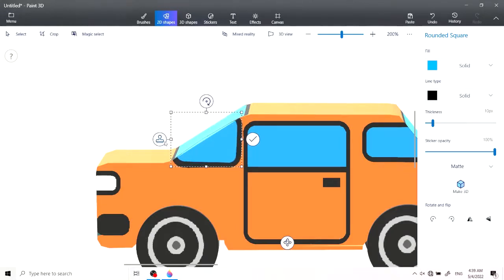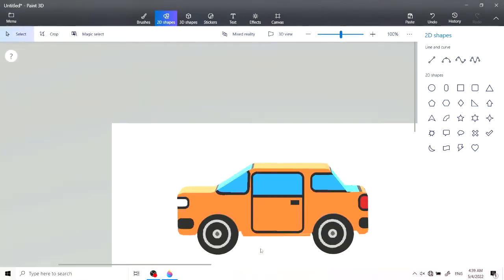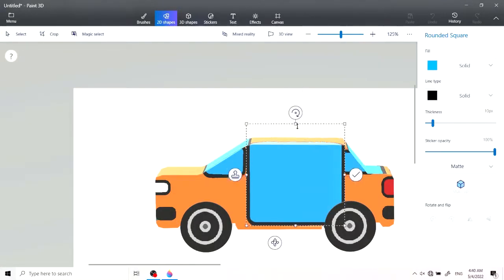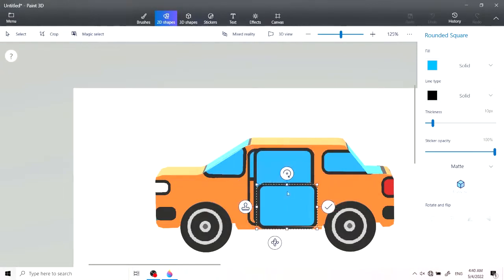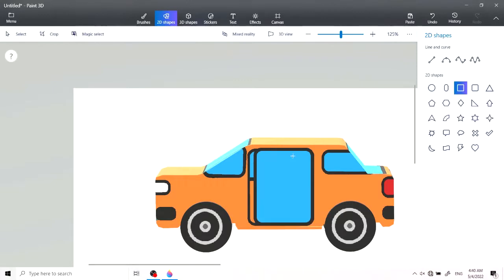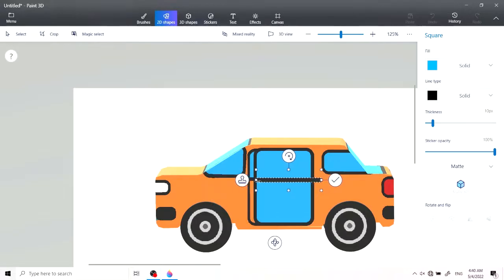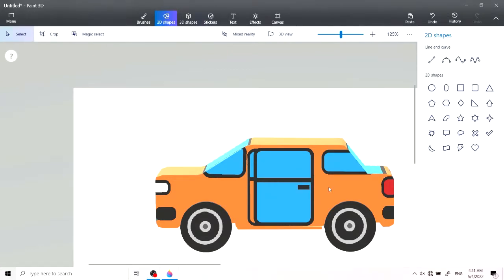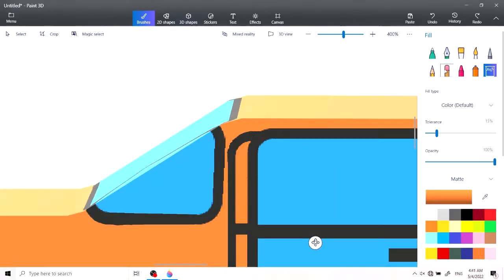But unfortunately the door is a little bit too close, so I'm going to need to correct the door as well. So I will use the geometric shape with fill in feature activated, and just align it over the existing door. What I did with the panel there, because I still had the panel active, I just pressed escape and it cancelled that panel. Then I used a more rigid square shape to create that line through the door.